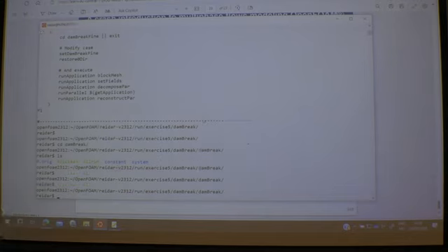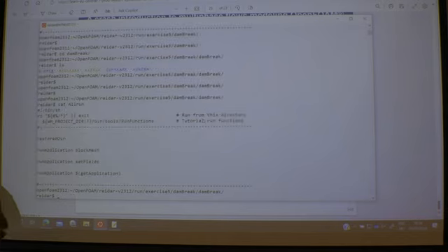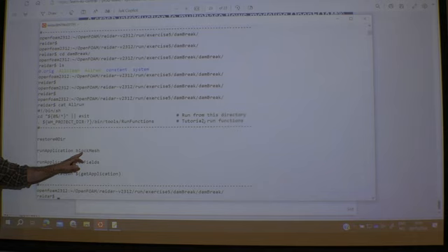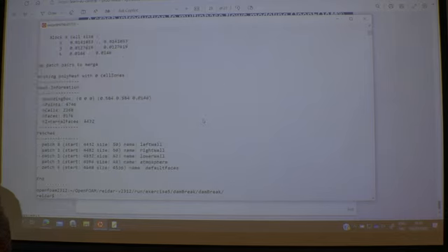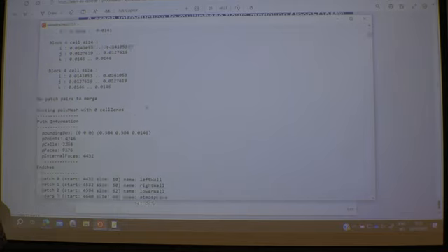So here, okay, there we have another Allrun. Let's have a look at it. Much simpler. So it's fairly straightforward. We have a blockMesh, something called setFields, and then we run. So let's have a look at this setup. Try the blockMesh first. And it's a fairly cute little problem. 2000 cells, not that much.